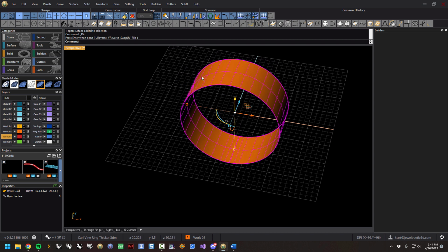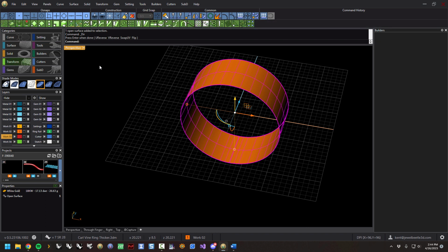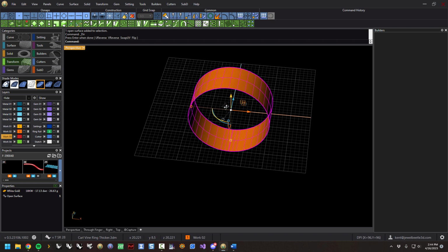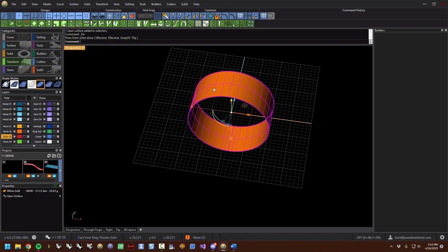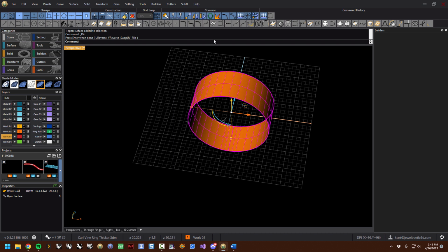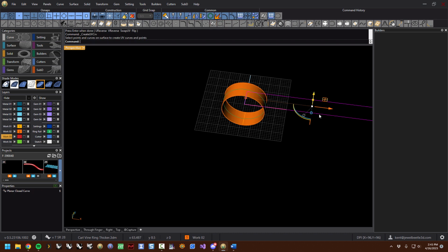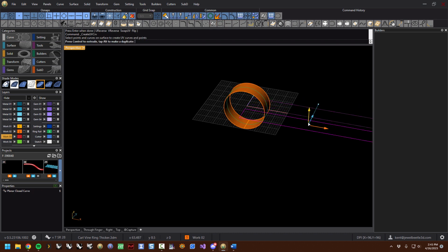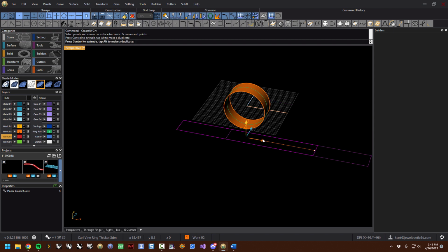In order to do flow along surface from Rhino, which is right here, this is flow along surface, you would need to create the UV curves from this surface. So we'd have to go to curve, go to UV and hit enter. And there is that surface pounded out flat, if you will.